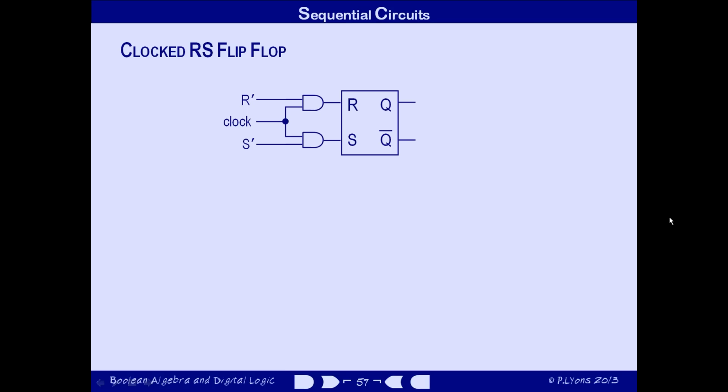Now, we know that there will be periods during which the data is being loaded into flip-flops and periods when it isn't. And if we do know that, then we can design the computer so that the calculation, which causes voltage glitches, and flip-flop loading, which is sensitive to glitches, happen alternately. That's at least a partial solution to one of the problems we mentioned earlier, that RS flip-flops are susceptible to loading unintended data values when glitches occur.